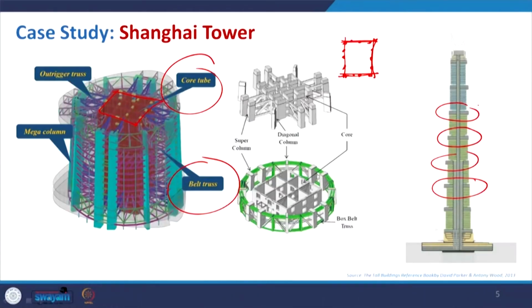Now, coming to the next example, before coming to this example, let us also discuss the profile of that building. It started with a larger cross section, and then at a certain height the cross section also gets reduced, and this is basically to tackle the lateral load. When we discussed the shape, like a pyramid or conical shape, it will have better performance against the heavy wind load at the top, and the reduction in mass at the upper stories definitely helps to make the structure more stable.